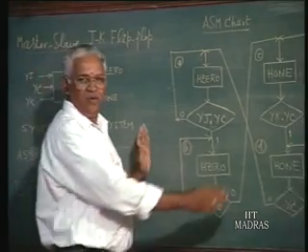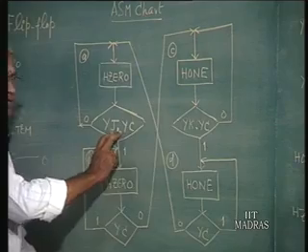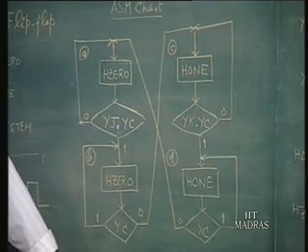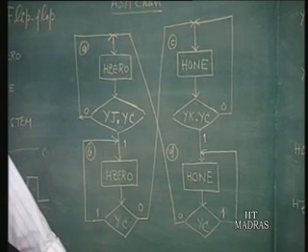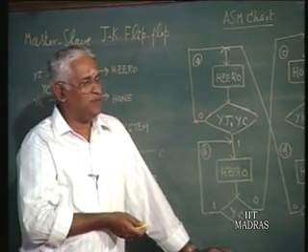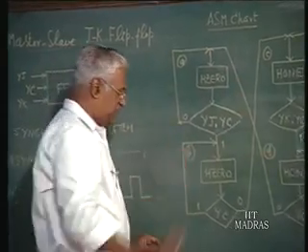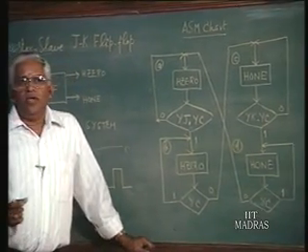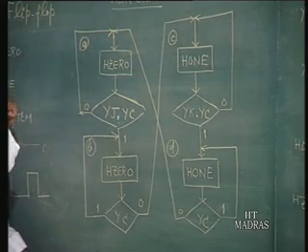Now here we have a 4 state machine and we have 3 inputs to be checked and 2 outputs to be generated. So with this we will try to see what is a microprogram control and what is the hardwired control, because it is easy for us to discuss and deal with. Good. Now because there are 4 states, I can now implement the memory element in the state machine.